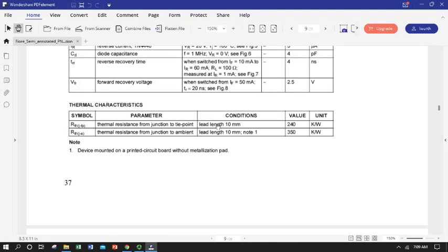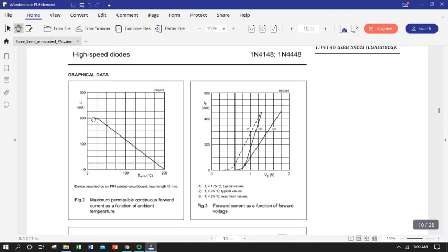Thermal, this is kind of going back to what not to do. Thermal resistance of our leads in the device, basically how much heat we can dissipate. And now some more graphs about performance, mainly with temperature. So how does our forward current change with temperature? And you notice, unlike the reverse bias, now we have the current going down with temperature. And this has to do with the temperature coefficient in the exponent term in our diode equation, and also allowable power dissipation.